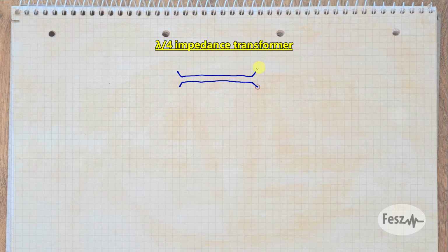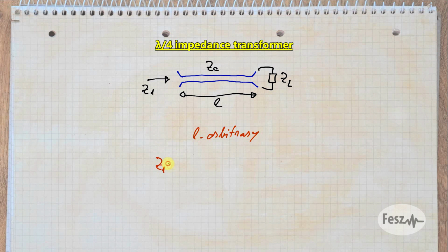The last thing to point out regarding this topic is that even if you use an infinite number of sections, you will still never get an infinite amount of bandwidth. To better understand this, let's go back to how a piece of transmission line works when it's connected to different end impedances. The transmission line will provide an impedance transformation based on this rather complex formula. This is quite useful to compensate for various complex loads.